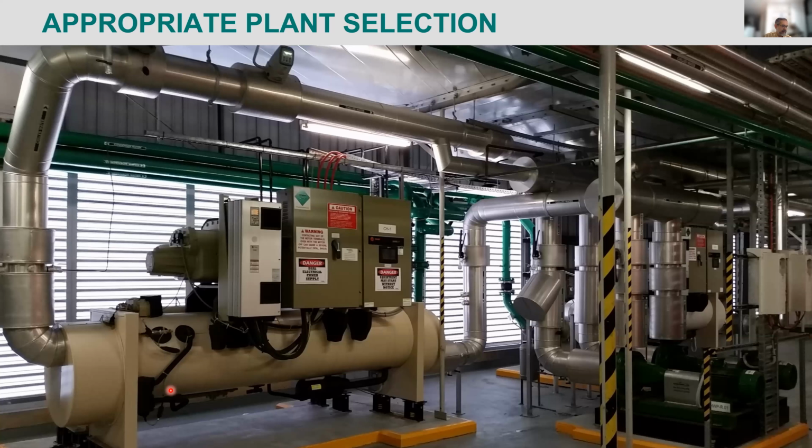And the reasoning behind that was because it was such a humid place, we wouldn't get a lot of what we call condensing water depression. So you wouldn't get cold condensing water temperatures because of the humidity in the air. So we didn't really need the most efficient chillers. We needed good and efficient chillers, but not the most expensive ones.